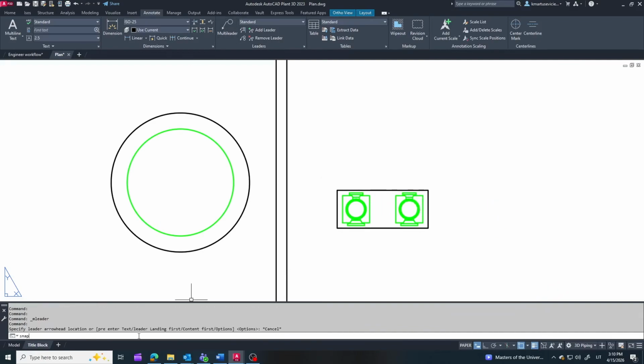One more tip: if your cursor moves in fixed steps, like a grid, and you can't select certain points, it means snap or grid is turned on. Just turn them off in the command line, and you'll get full control again.